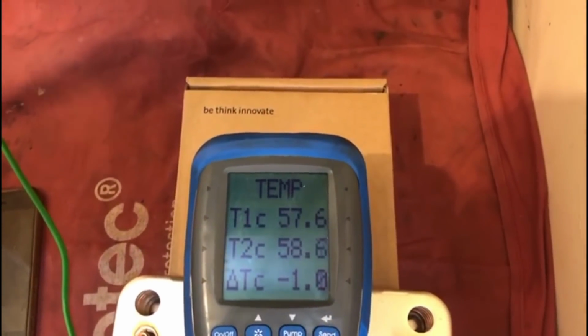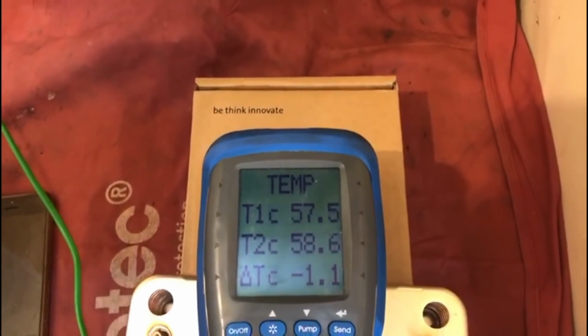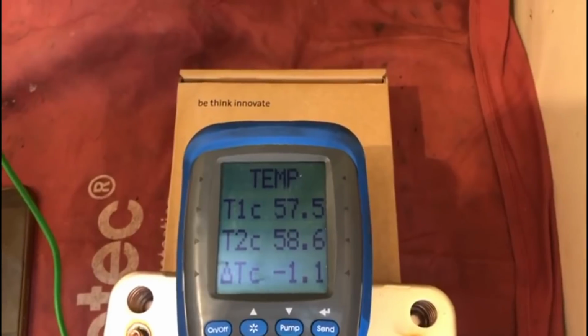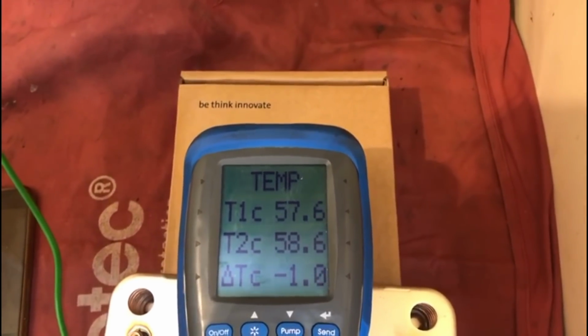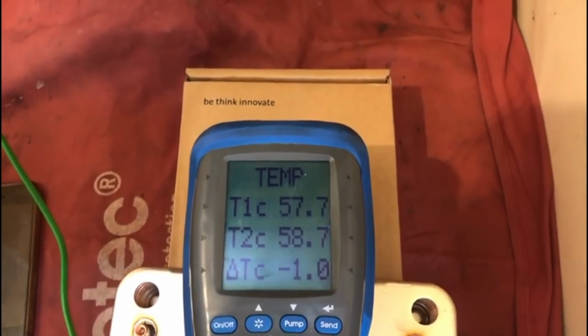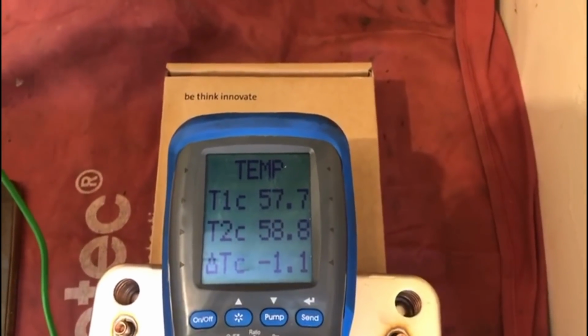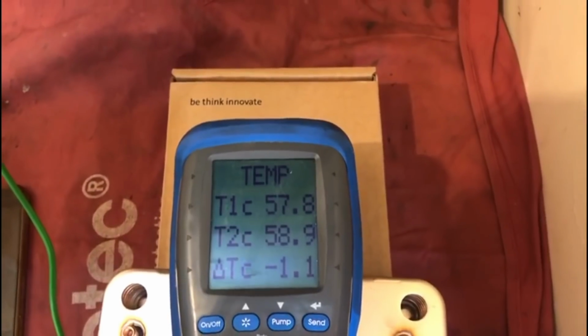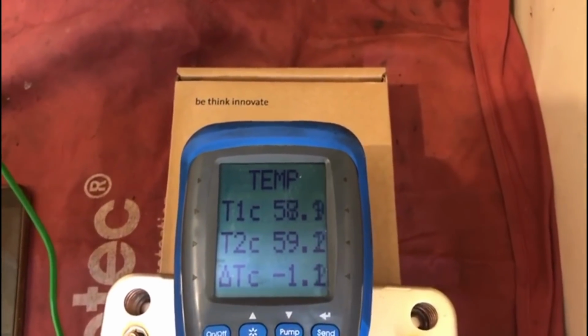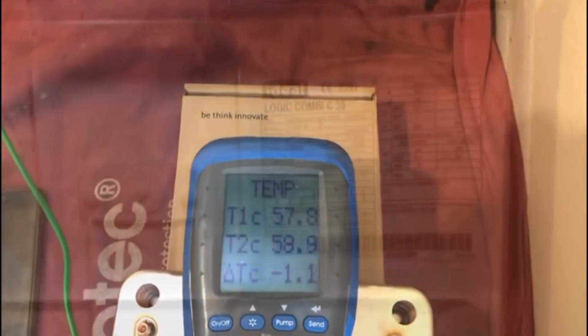That is a perfect way of saving you time and effort of taking it out and physically looking inside it to see whether you can see magnetic iron oxide, microbial bacteria, non-magnetic particles, calcification, lime. There's plenty of things that can restrict the plate heat exchanger, but this is definitely the way to prove that it is restricted. So I hope this helps.